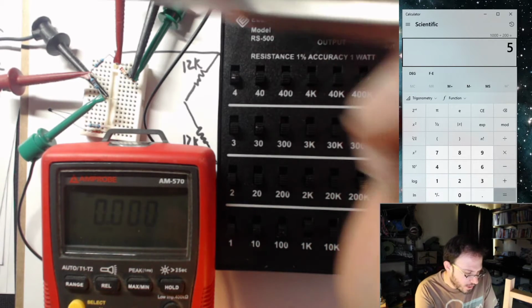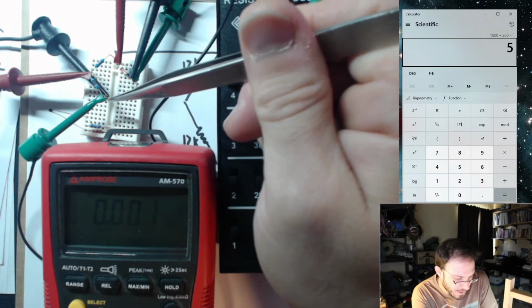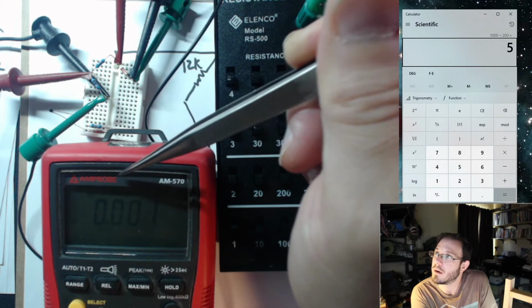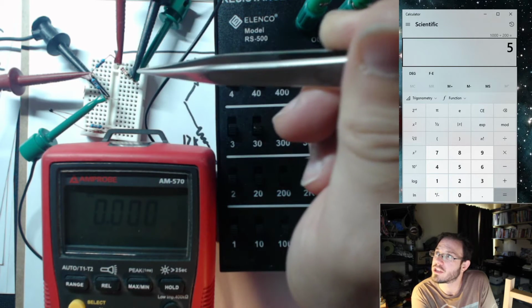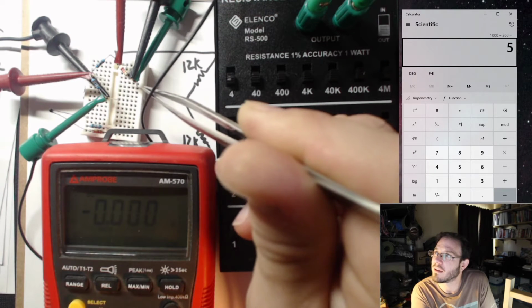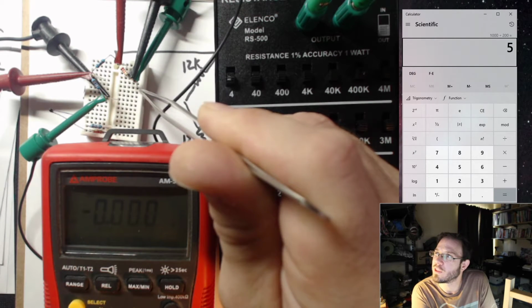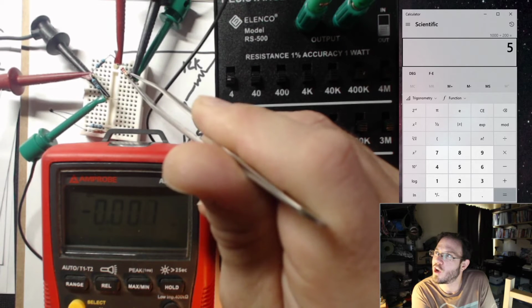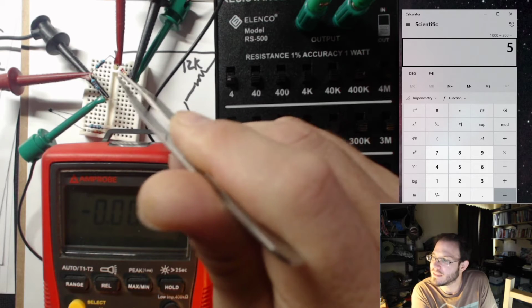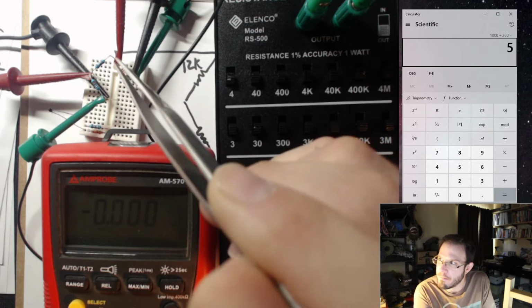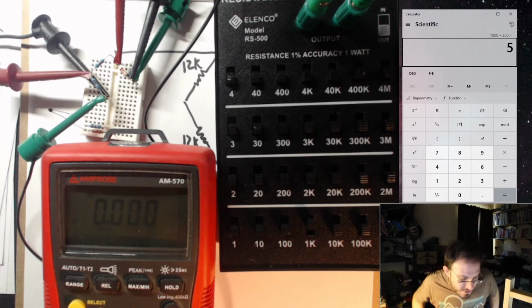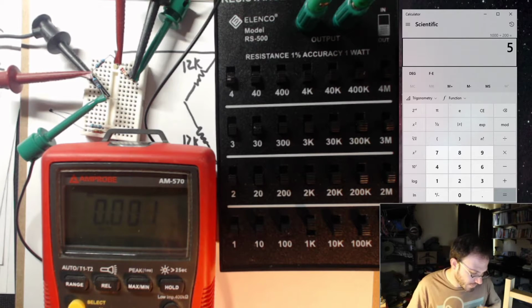Okay, just to reiterate connections, I have positive and minus of my 5-volt source connected to the top and the bottom of the bridge. I have my multimeter measuring voltage between the left branch and the right branch, and I have this substitution box acting like my resistance standard between the right side of this unknown resistance and the bottom here, and then I have an unknown resistance over here that we want to measure. So we want to measure what the resistance of this unknown is.